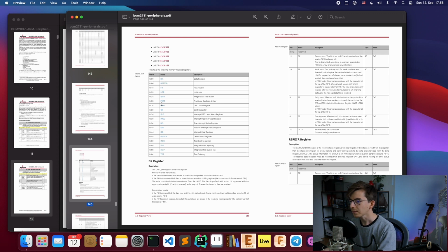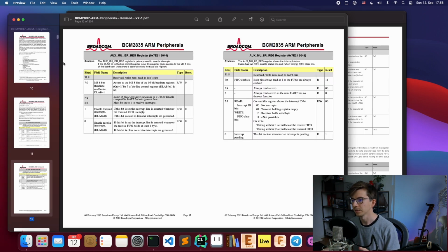And anyone who is familiar with programming microcontrollers on low level, not Arduino scripting, but C programming for STM32, for example, gets a lot of familiar feeling, because you need to control registers directly, set certain bits and bytes to certain values to get the result.